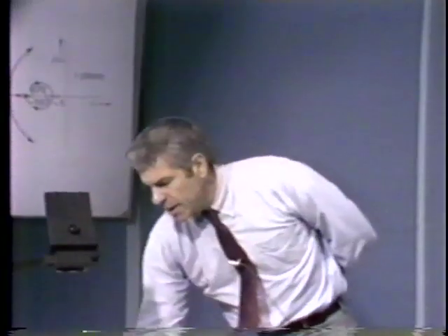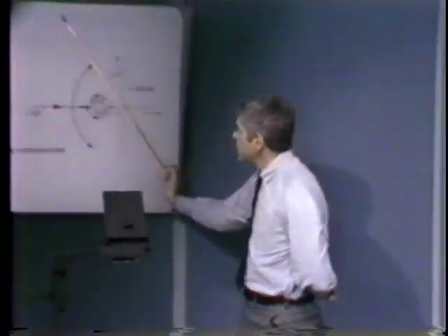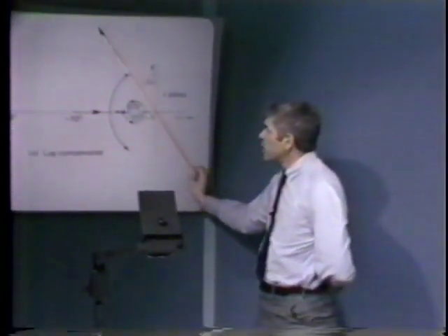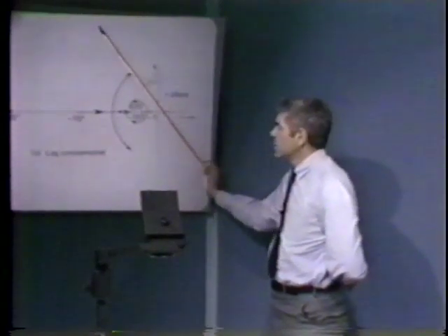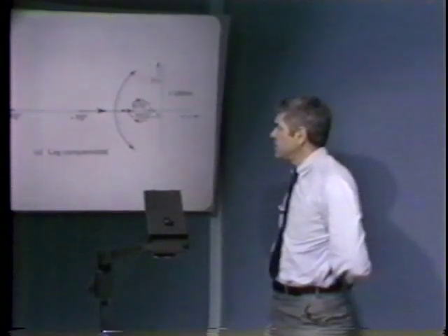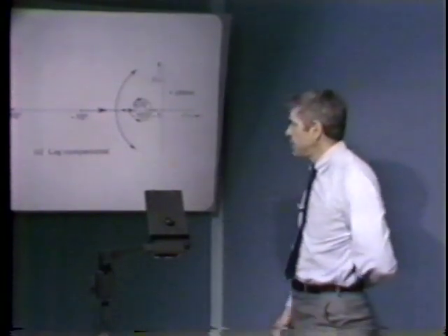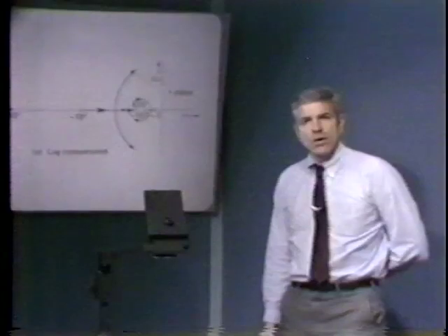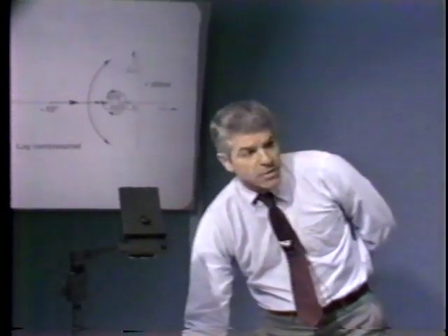However, if we kept track of A0, F0 necessary to get out to a given damping ratio, we'd find out that we could tolerate considerably more A0, F0 in the lag compensated case than in the uncompensated case. In fact, about a factor of 6.2 greater A0, F0, equal to the alpha of the network that we use.